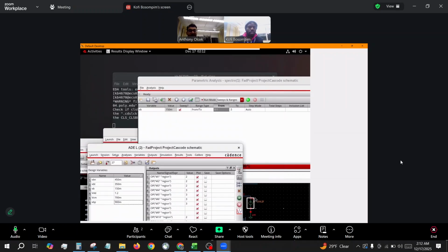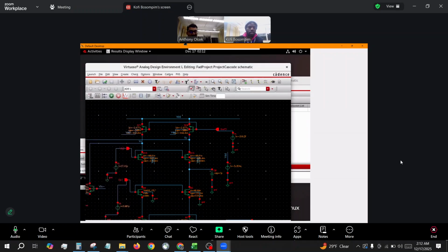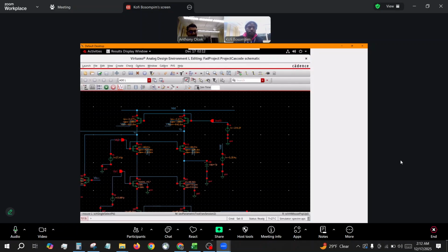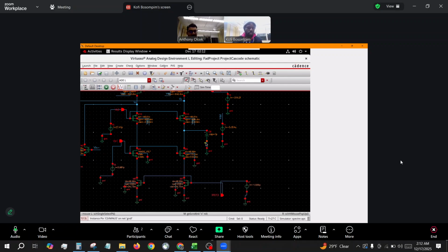So, regarding the question of increasing the output capacitance, we found increasing it to 20 pF, by moving the dominant pole lower, we were able to increase the load capacitance and reduce the bandwidth along with the unity gain frequency. And the phase margin we found almost stayed the same because of the internal non-dominant pole. It didn't change. In order to improve performance for gain, we decided to increase cascode channel length.